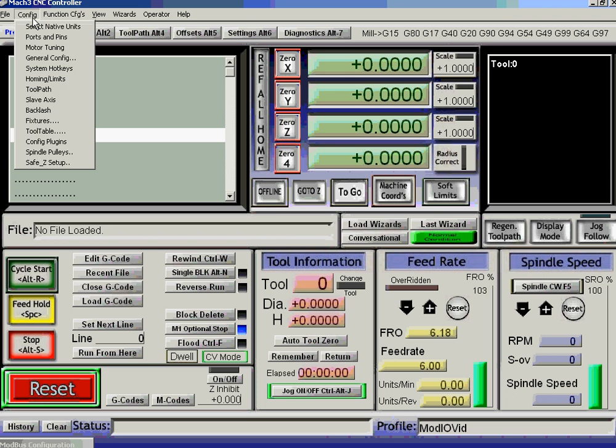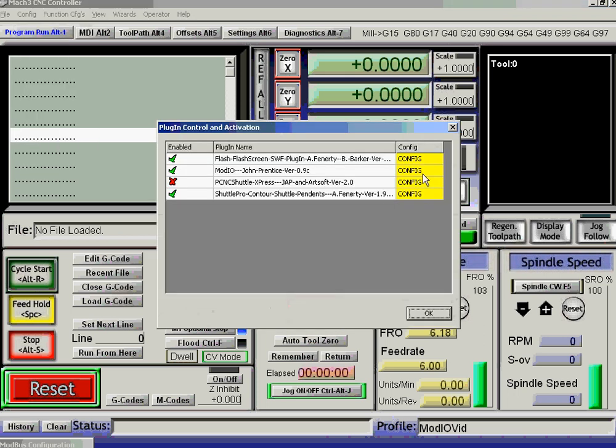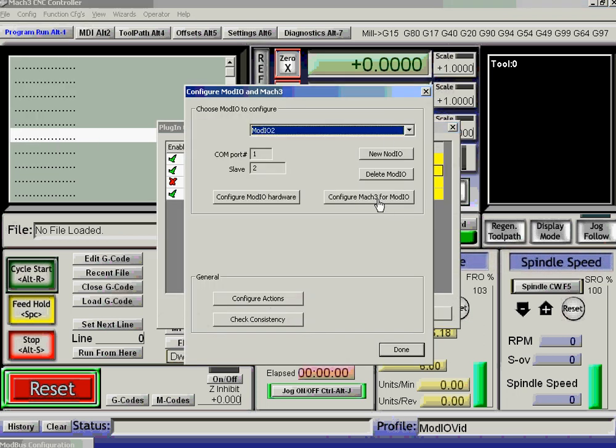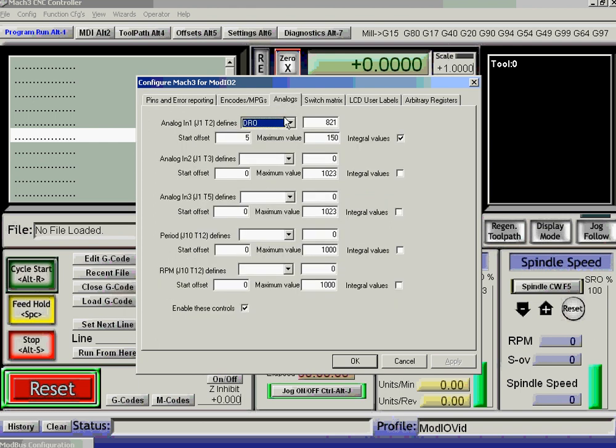One of the other good things you can do with an analog input is configure it so that it is integral values. If you put the value into something like the spindle pulley number and have a multi-position switch with 4 positions, say, and 4 resistors that give you 4 inputs, you would then choose an offset which went from 1 up to 4 and have integral values.